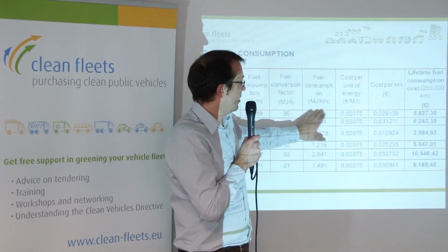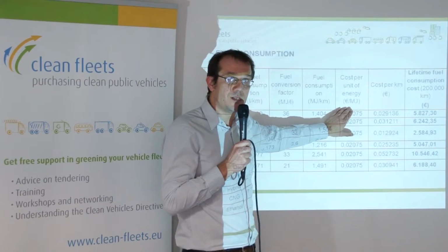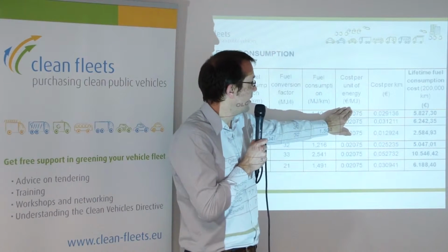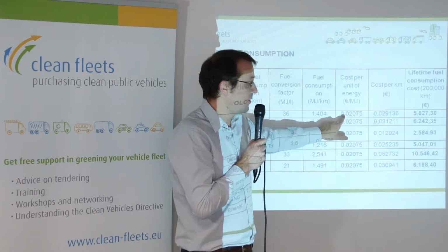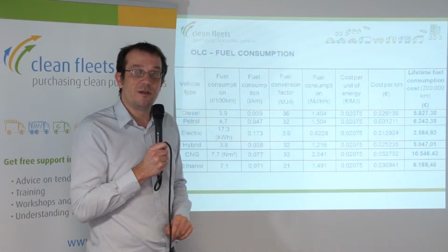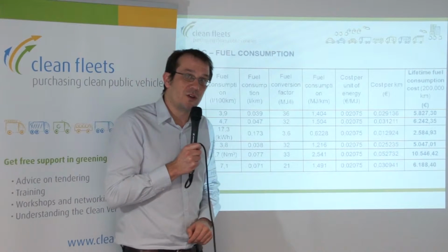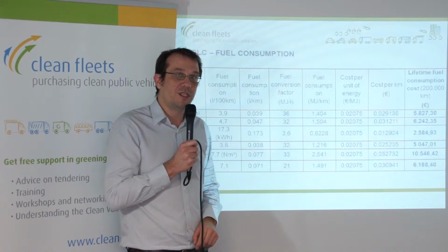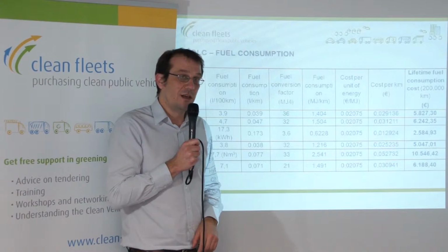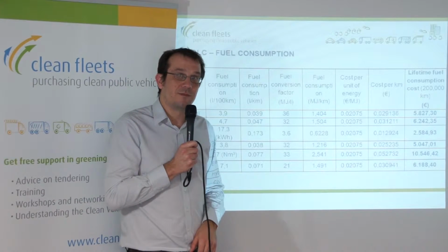Once we have this figure, then we need to know for calculation purposes what is the cost of a unit of energy in euros. And this figure is again prescribed by the Clean Vehicles Directive, and the figure should be the cost of a litre of either petrol or diesel, whichever is cheapest, and that cost before tax.